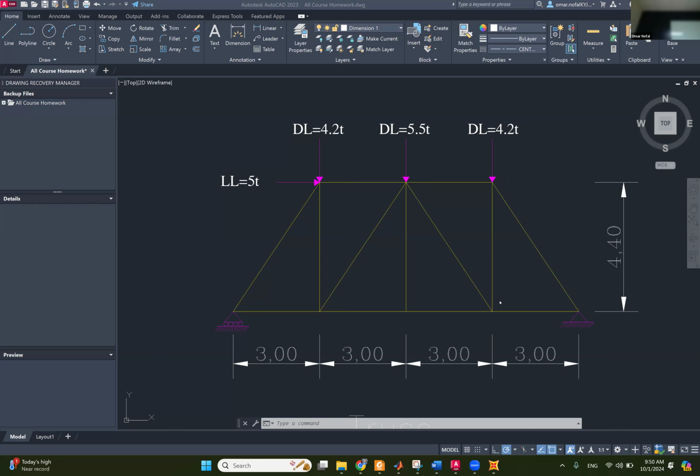Okay, so this is the first application that we have, a truss. But before I do the analysis for this truss, is it determinate or indeterminate? Determinate, right? Externally, I have a roller and a hinge, so it's three reactions, so externally it's determinate. Internally, that's how a determinate truss actually looks. But if you found another member going that way and they are crossing each other, that means there are extra members that this truss doesn't need, right?